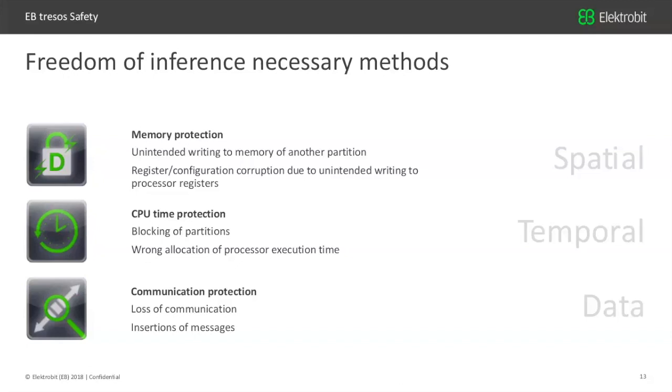Here I monitor the execution time on the processor where my software runs, so it doesn't overrun or get stuck in an endless loop. And I have the communication data protection domain, where I need to protect the information, so the interfaces which bring information in and out of my software function which has a safety impact.